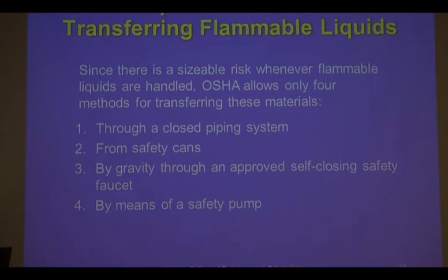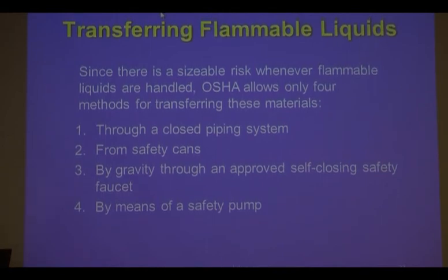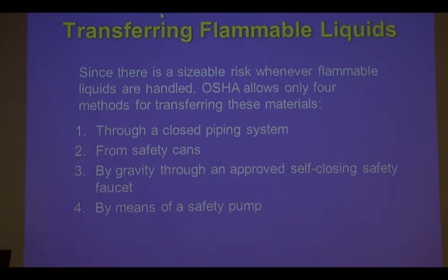Transferring. This is starting to be an issue. They talked about this at my OSHA training. They're starting to get more and more OSHA violations for transfer of flammable liquids. Okay, there's only 4 methods of transferring flammable liquids. I think I put this on your handout too.